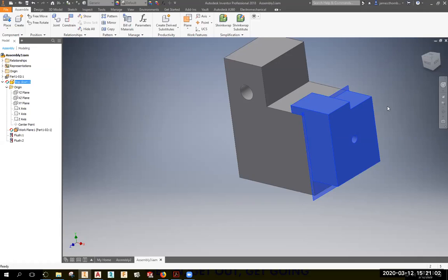Okay? So you can do this also. Or you could start the pieces, put them together, and then finish the pieces. That's called middle out. Okay? So either bottom up, where you draw the parts separately and then put them together. That's kind of what we've been doing. You can keep doing that, or you can do it like this, where you model it in the assembly and go down, top down. Either way is okay. But they do need to be separate part files.